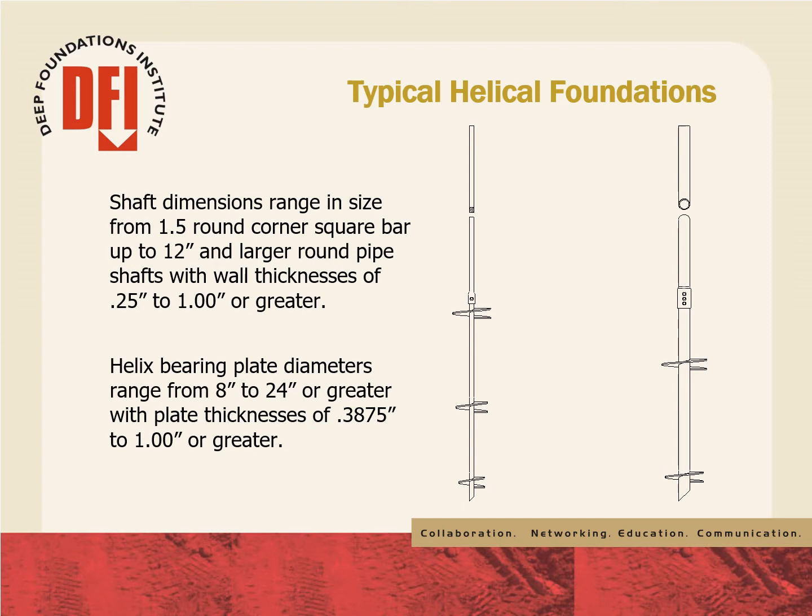The shaft sizes range from 1 1/2 inch square bar to 12-inch diameter and larger pipe shafts. Helical plate diameters range from 8 inches to well over 24 inches. Lengths vary, but can range from 7 feet deep to well over 100 feet long.